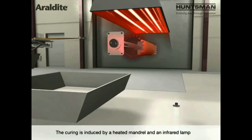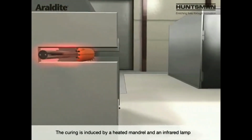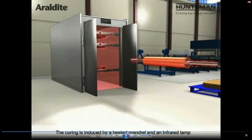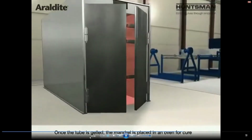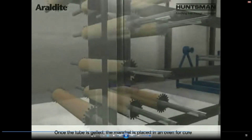The curing is induced by a heated mandrel and an infrared lamp. So the mandrel is also hot and an infrared lamp is used to further perform the curing operation. Now curing, as all of you know, is the polymerization process, specifically in case of thermosetting type of resins. The curing is induced by heated mandrel as well as the lamp. Now once the tube is gelled, the mandrel is placed in oven for curing.